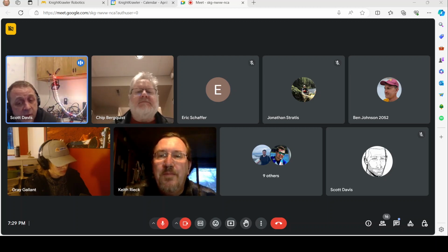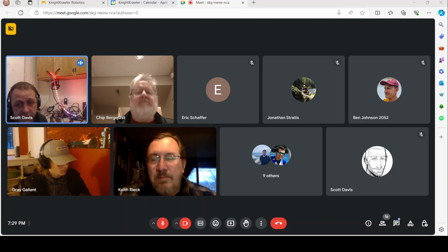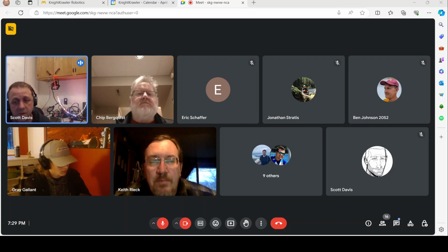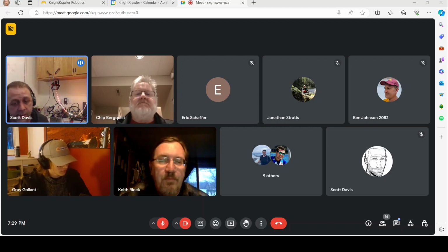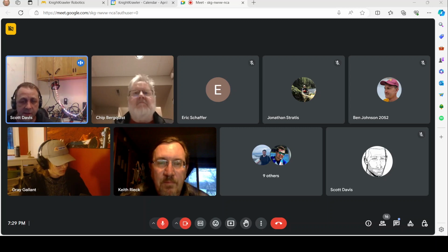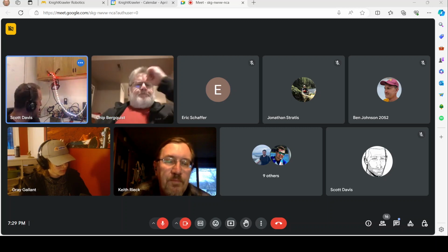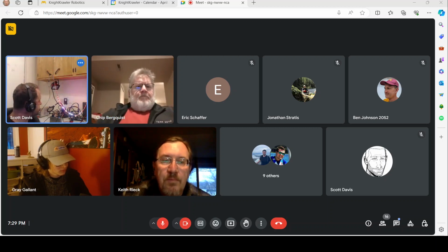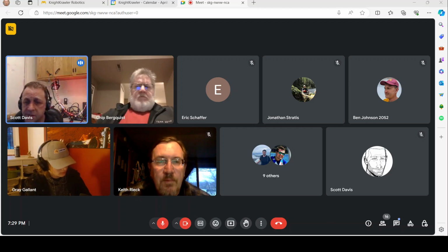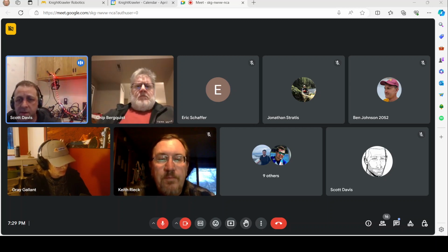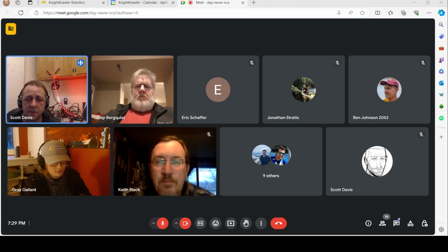So, I mean, there's no reason why you couldn't. I think what Keith's saying here is that if you wanted to hook up a bunch of limit switches or other sensors to your Arduino, you could have your Arduino or Raspberry Pi or whatever you want communicate back to your RoboRio if you need to take some processing power off. That's why we run PhotonVision on a different chip, to take some processing off of the RoboRio. That would be an option. Anyone else have any questions about the hardware setup here before I move on to some code?